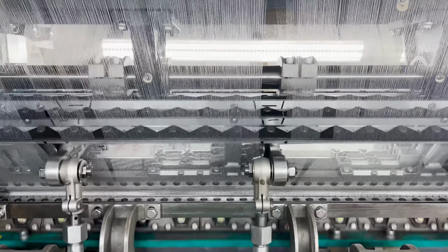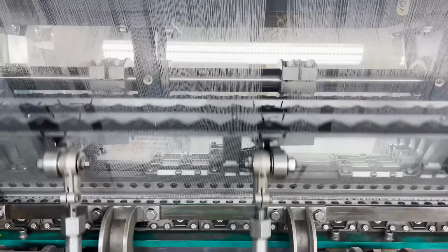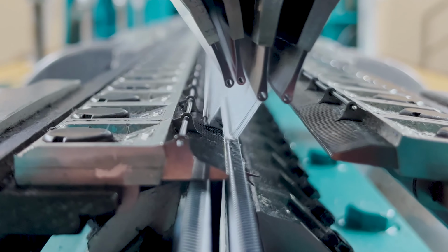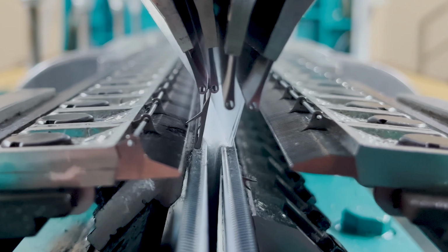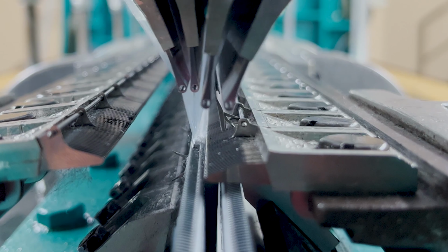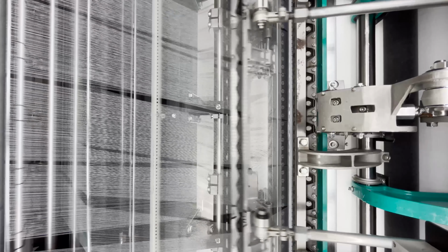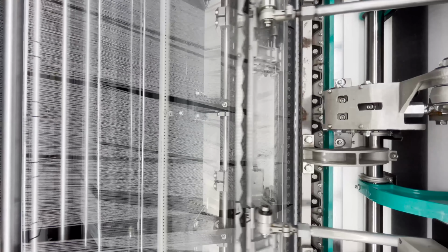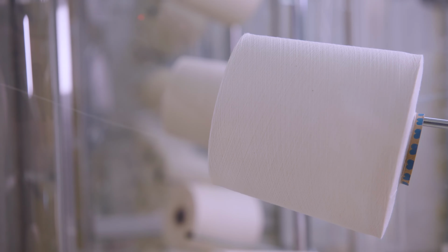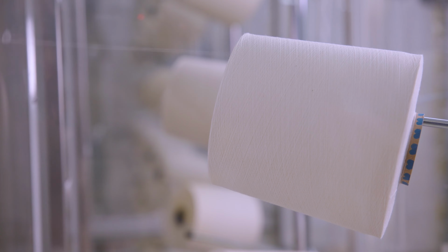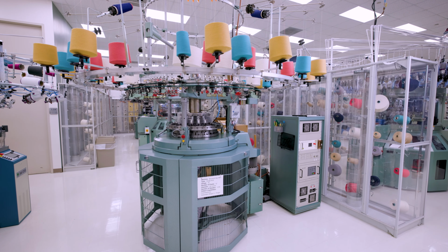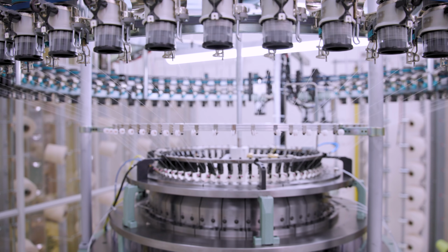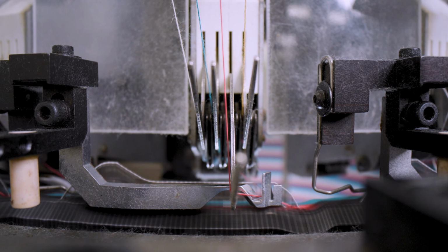With warp knitting, individual needles knit simultaneously across the width of the machine. Loops are formed by needles knitting a series of warp yarns fed vertically and parallel to the direction of the fabric formation. Warp knitting machines are very productive, but warp knitted fabric often requires very large production runs due to the lengthy machine setup. The unique properties and wide varieties of knitted fabrics keep them popular for both consumers and the industry. A solid understanding of the different types of equipment and capabilities will help you select the right product and production method for your needs.